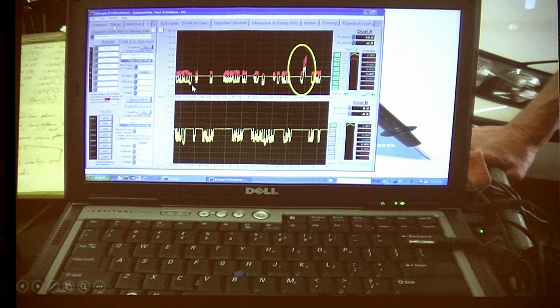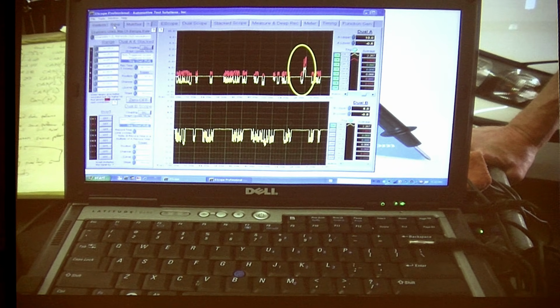I want it slow so I can watch the packages run across the screen, so if one jumps up or down, I see it clearly and quickly. This isn't about looking at the bits. I'm not interested in getting the scope so fast I'm looking at these. Are the bits going to do me any good? It ain't going to fix the car I'm working on, guys. It might fix yours, but it doesn't fix mine.